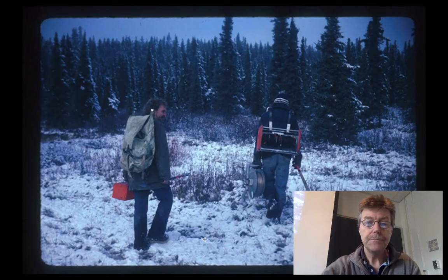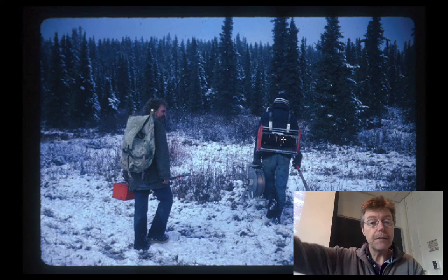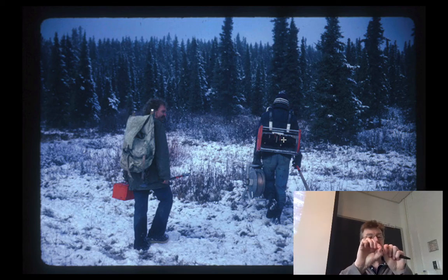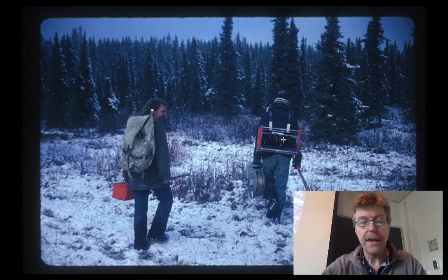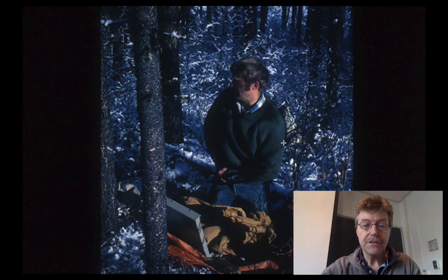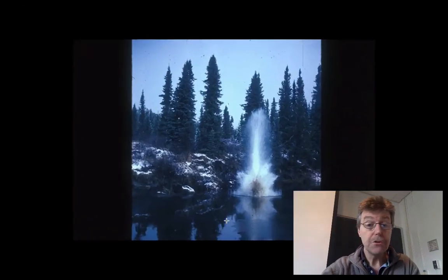They're pretty mobile. So these are the cables that are used. These are a reel of cable. They will take the cable out over a couple of hundred meters. That actually has connections where you just attach these individual geophones, maybe at 30-meter intervals along the length of the cable, once you put it out. You have all that fed into this seismograph, which is recording it, with your jacket there so that you can put it over your head and so that you don't have the sunlight disturb you.